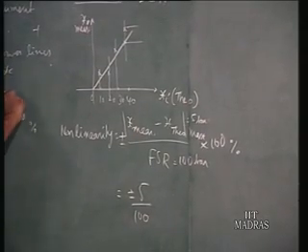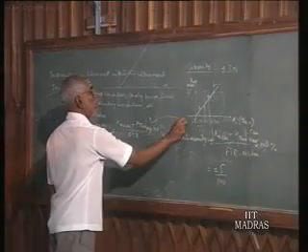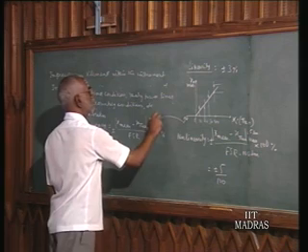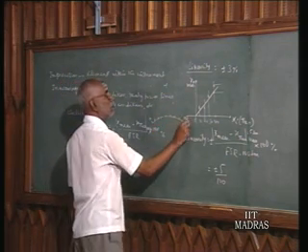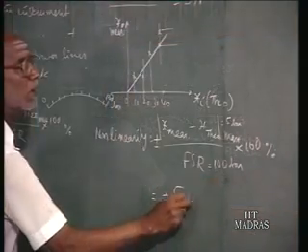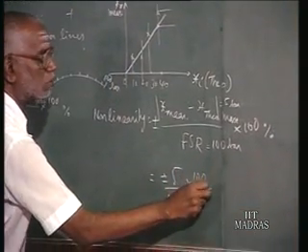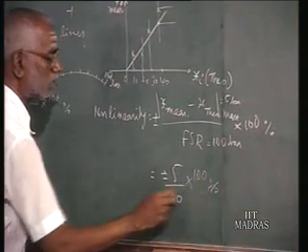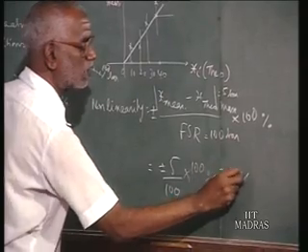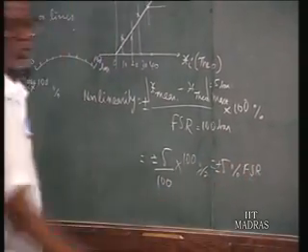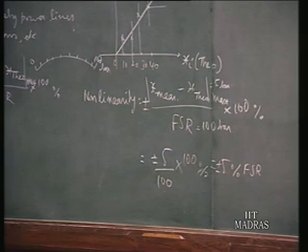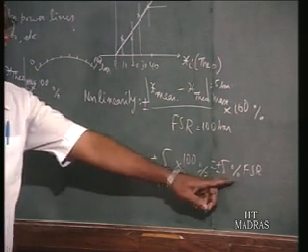The instrument scale is here: 0 bar, this is 100 bar. So this is the maximum full scale reading of the instrument, 100 bar. That is what you are supposed to put, into 100, that is percentage, plus or minus. So it is equal to plus or minus 5%. Whenever you are using the full scale reading for the definition, always write plus or minus 5% full scale reading.